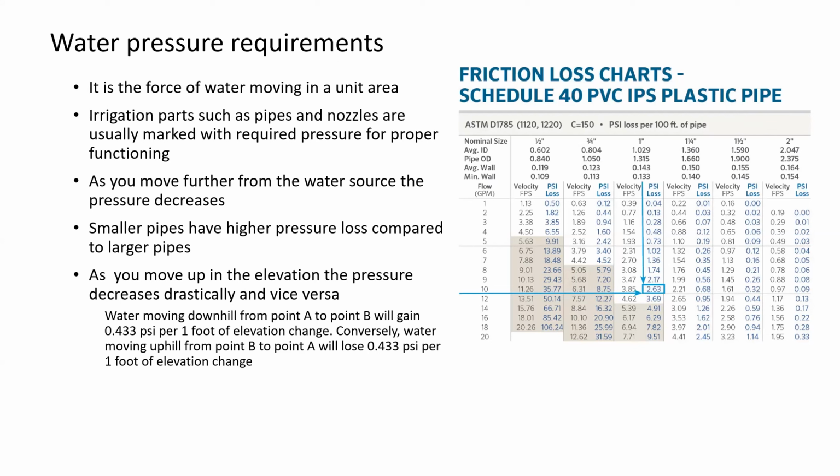Now we can put a pressure check valve, a regulator valve, at a water source and say, okay, this looks like 35, 40, it's good for my drip irrigation. But it's not that simple. As a small farm producer or in an urban setting, you might have a large production area and the pipes might be running maybe 100 feet or maybe 200 feet, and you are using risers, pop-up emitters, maybe a drip irrigation system on those pipes. Now you need to understand that as you move forward, or as the pipes get longer, there is a reduction in pressure.